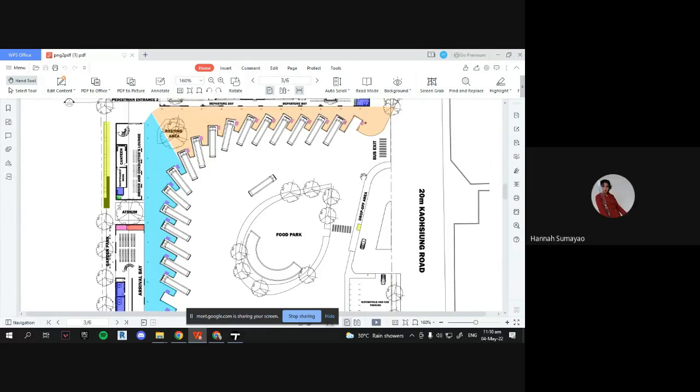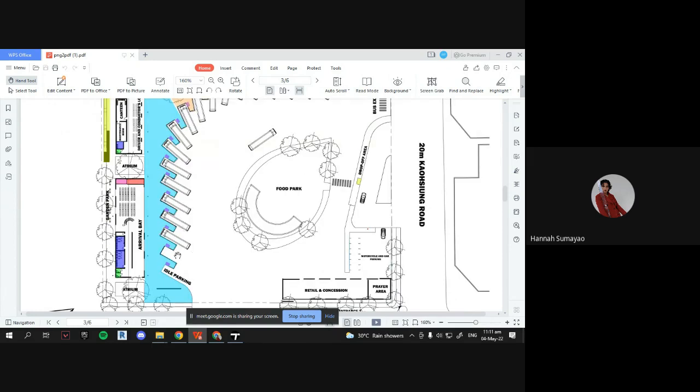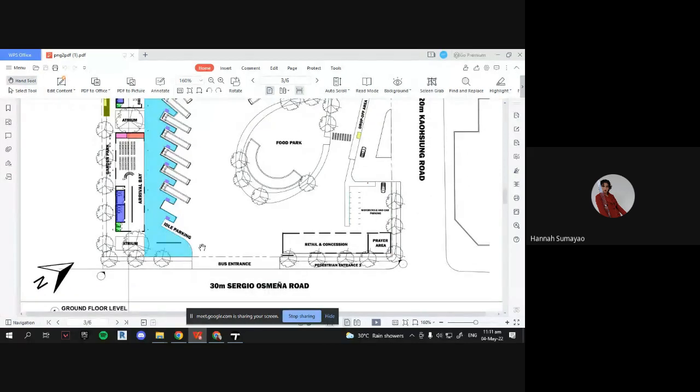I apologize for that. So, drop-off area, this ramp. Then the violet areas there, sir, are part of my design concept for PWD. Most buses here have stairs rather than a ramp. There is no lowering mechanism on the bus, unlike in other countries. So I will just put modular ramps at the side. Then this can work as idle parking.